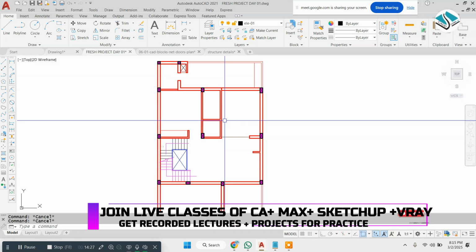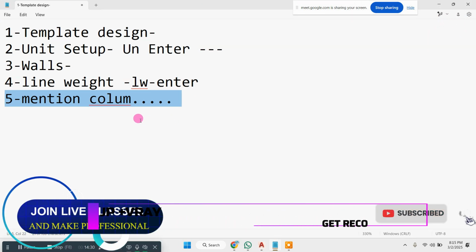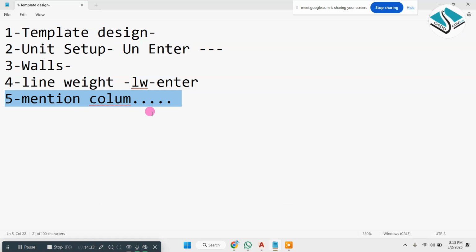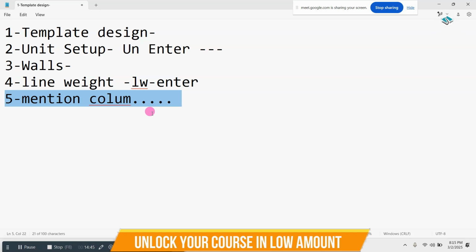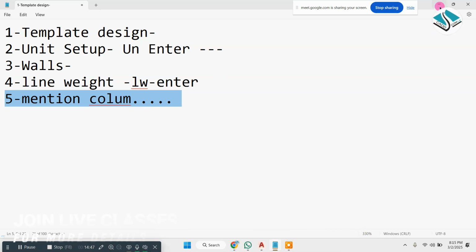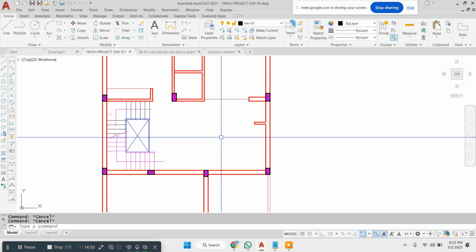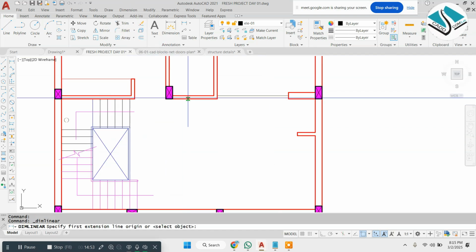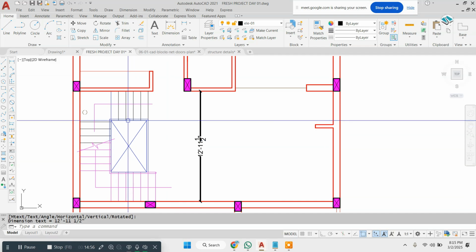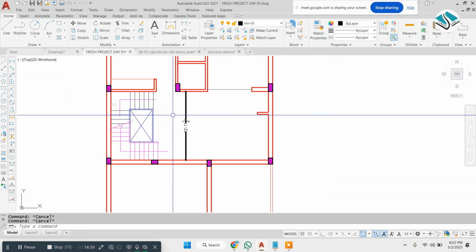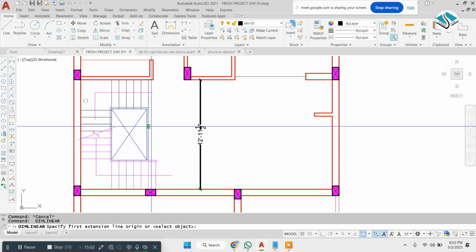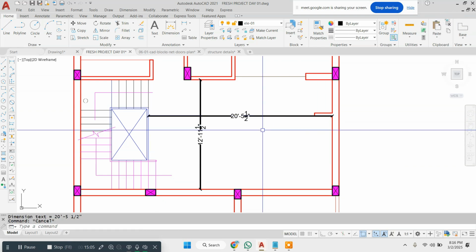Right? So the process is... Sir, I have one doubt. Sir, when we do a 30-40 plan like that, we can place the bedroom sizes and kitchen sizes easily. But when I go for the living room, I'm unable to get that measurement, sir. How can I know? Can you tell me? Living room, the basic space that we can use is approx, there are also some conditions. If you are placing a stairs area, then after placing the stairs you can use approx 20 by 12 as a standard, right?